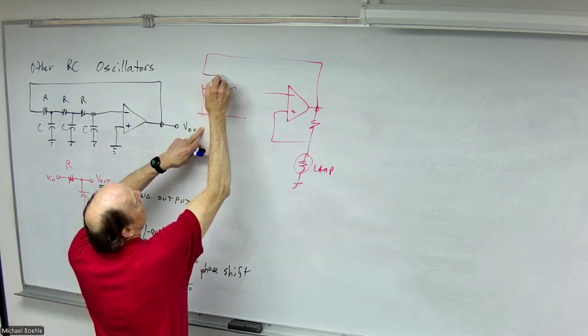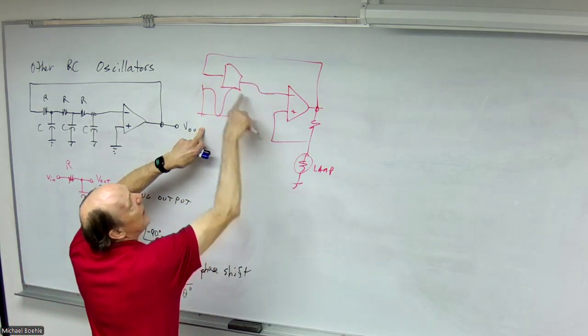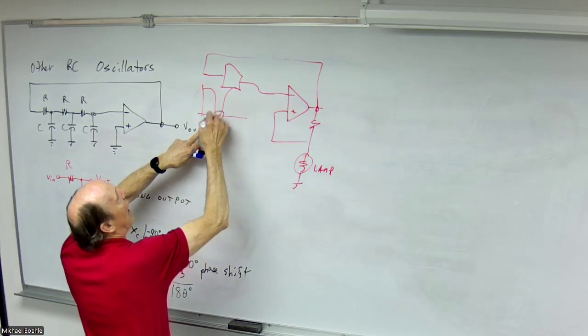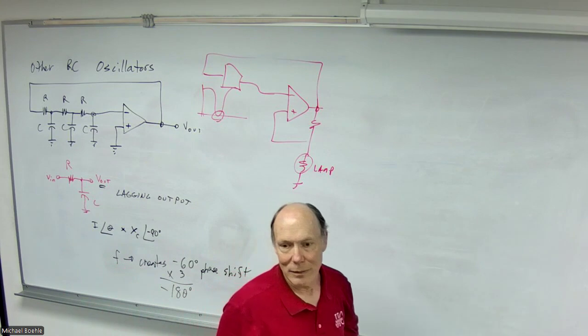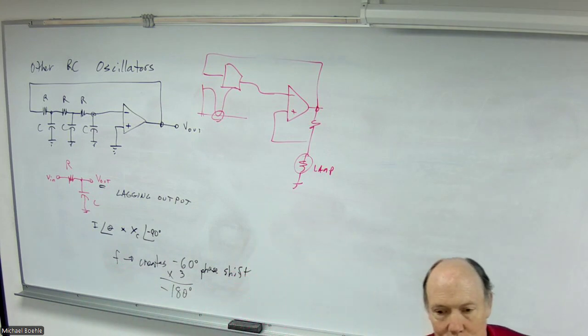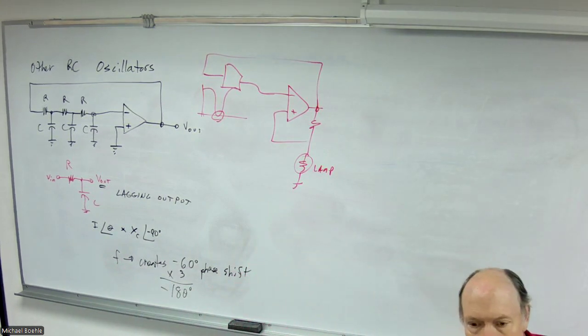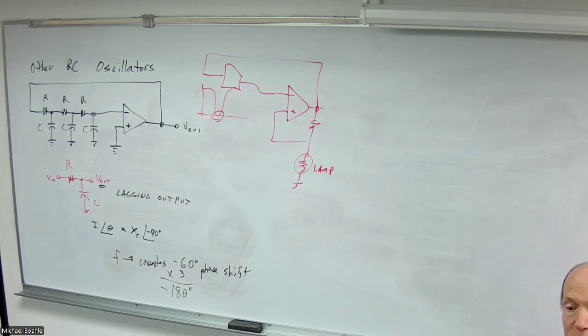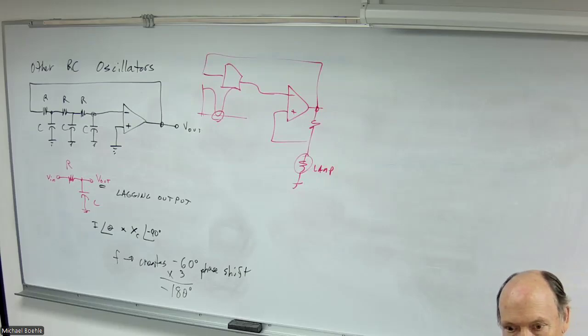Well, we're providing negative feedback everywhere but that frequency. Okay. So it's like the opposite effect. So not only is there a dip there, but there's also a phase shift that ends up being zero at that point. And so you get no negative feedback at your resonant frequency.